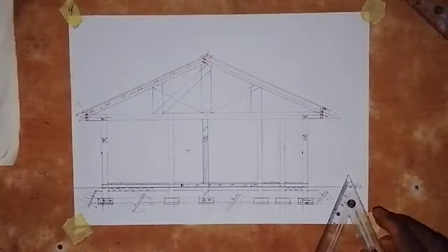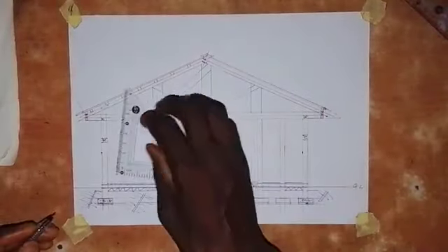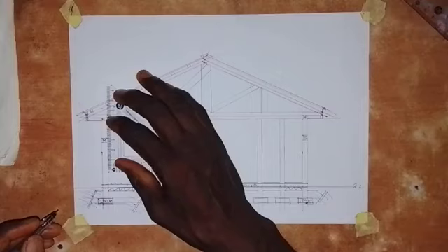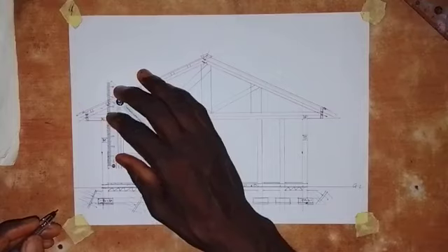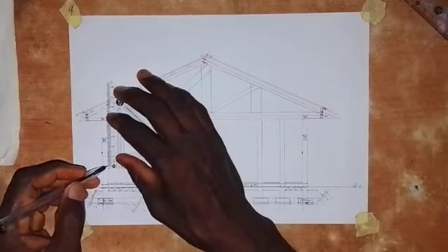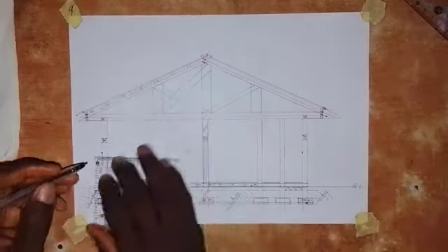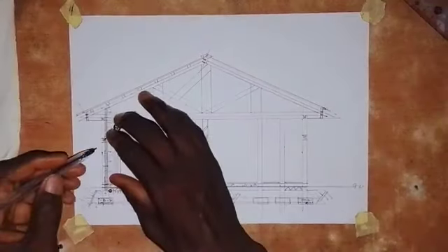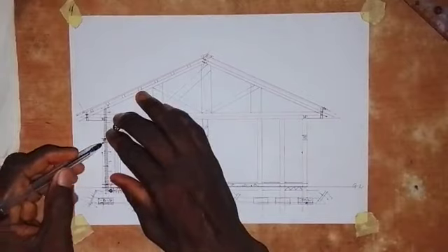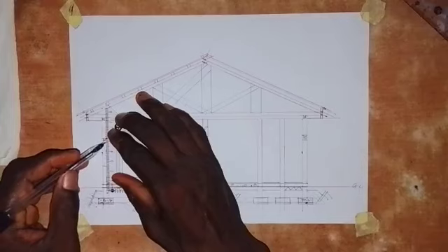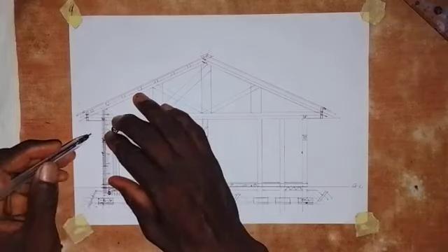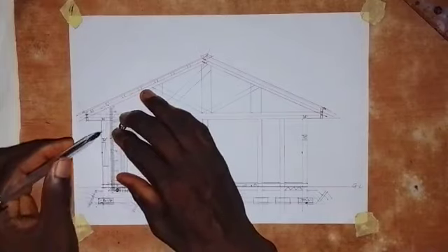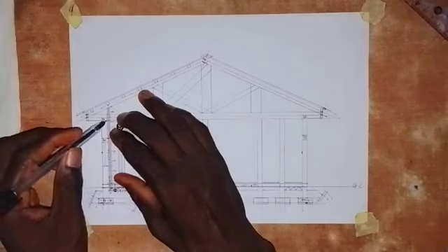I think it's 1200 by 1200, and that will give us 24 if we divide by 50. So this is 24 millimeters here. So we have it to be 24 millimeters. It is also cut by the cutting plane, so we draw 2 vertical lines within this space like this. Here we have put the window that is cut within the wall.